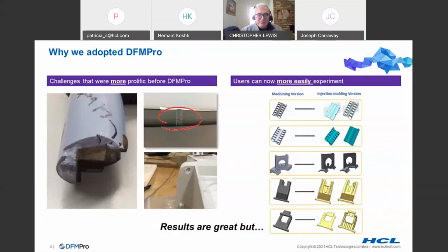So coming to DFMPro, we've been using it quite a while, 2013 in fact. I'll come back to that, but we've been seeing less and less of these types of things. A fastener embedded in the plastic too close, plus cleaners, plus stress can bring a factory line down, or maybe cavitation in the molds can be unseen in the final part, but again, over time with stress and cleaners. By the way, COVID cleaners are incredibly aggressive against plastic.